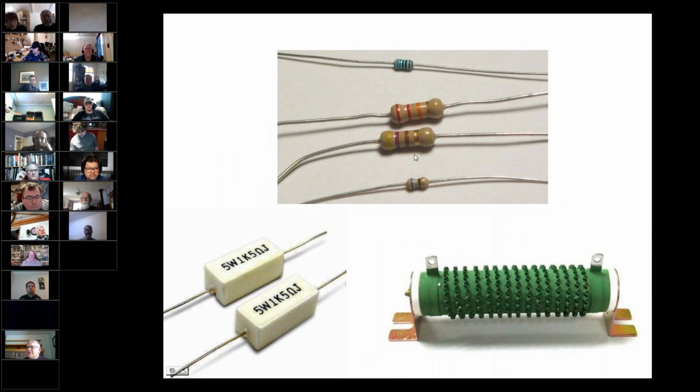Now here's what some resistors look like. These are the types that you'll see in most electrical circuits. The bigger they are, the more heat they can dissipate, so the more power they can handle. We'll talk more about that next class. The resistance can still be the same.